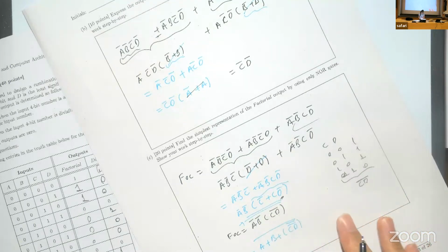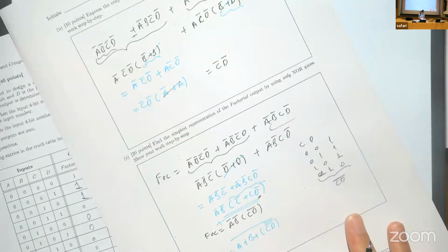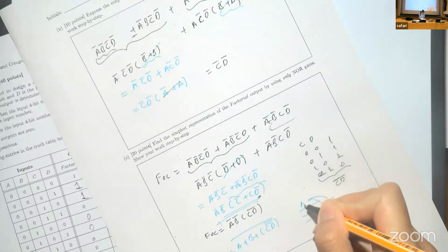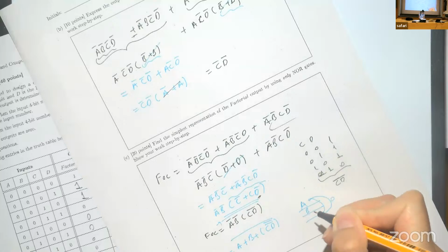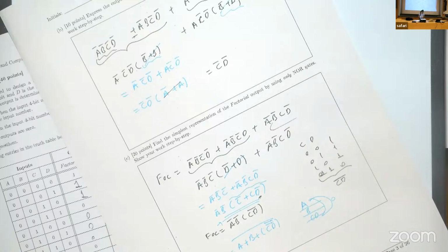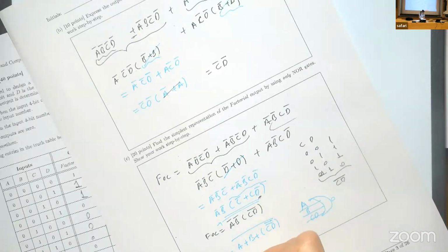Now we have almost everything in the NOR gate form. So if we have a NOR gate, we have 3 inputs now. The first one is A, the second one is B, and then the other one is CD. Because if you negate something 2 times, you get the original thing. But the thing is, CD is not in the NOR gate form. So we need to figure out how to express CD in the NOR gate form. And CD is equal to CD negated twice. We use the same thing, which is equal to C naught or D naught.